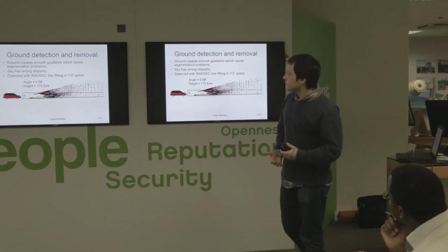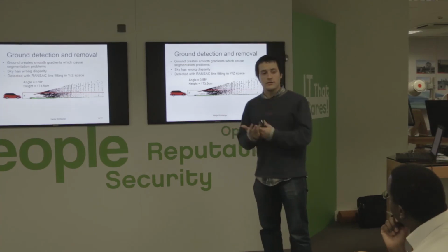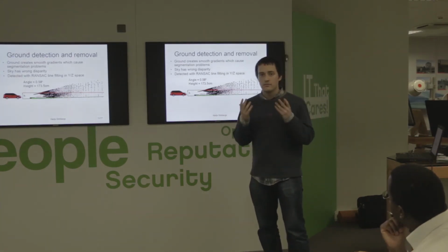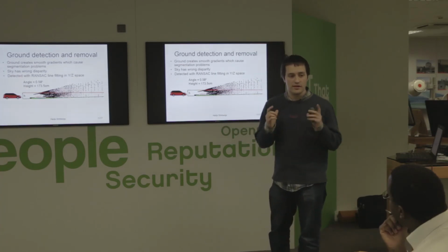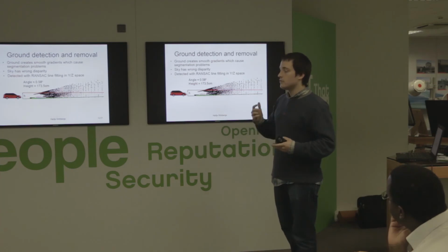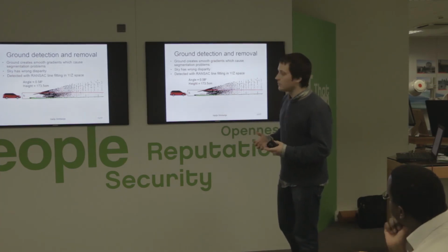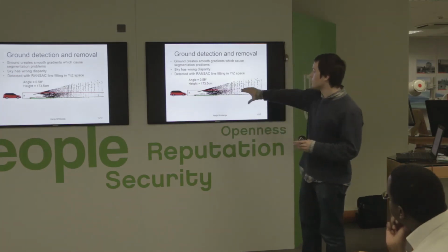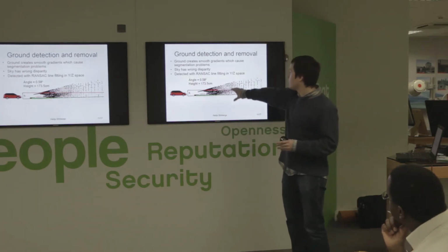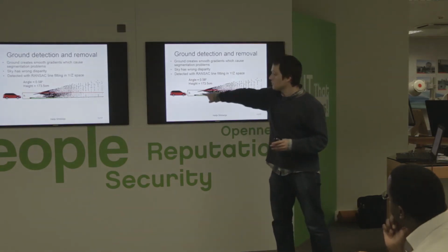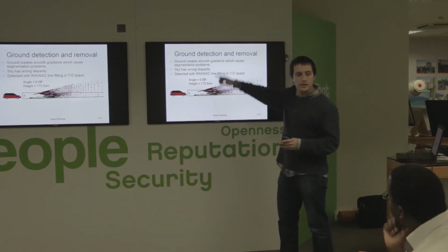It had to be done in real time and very fast. With up to hundreds of thousands of points in one point cloud frame, to get it real time I reduced the dimensions and looked at the YZ space, where Z is the depth direction and Y is the vertical direction.